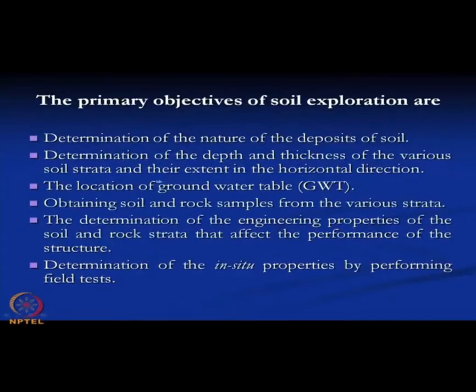Similarly, for the settlement calculation, the consolidation properties of the soil are also very important properties that we should know for the foundation design. Now, the primary objectives of soil exploration are the determination of the nature of the soil deposit, the determination of the depth and thickness of various soil strata and their extent in horizontal direction.